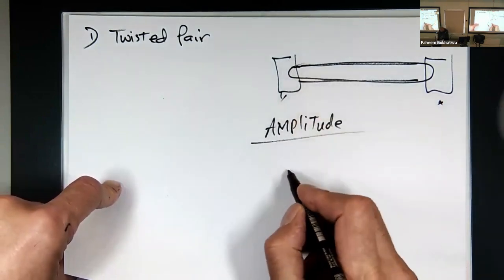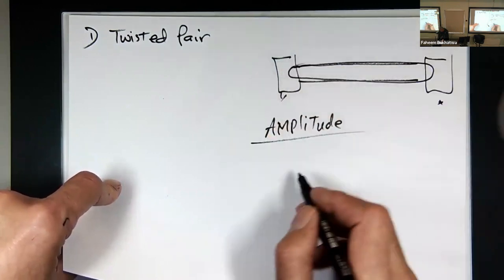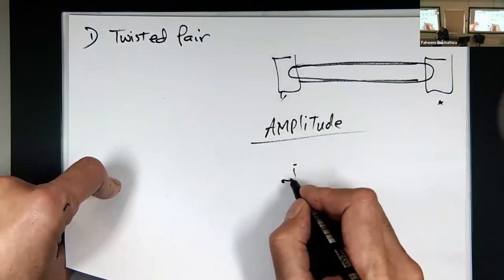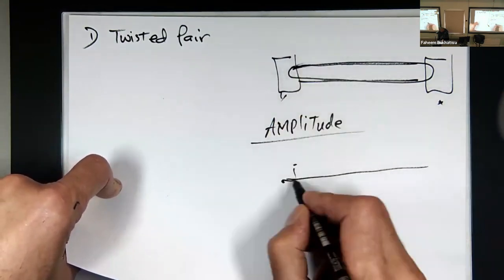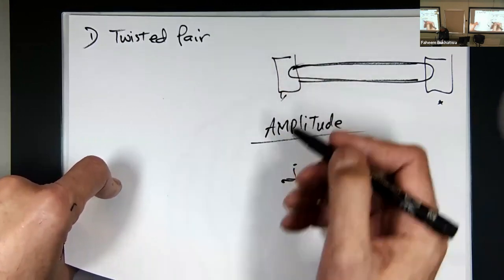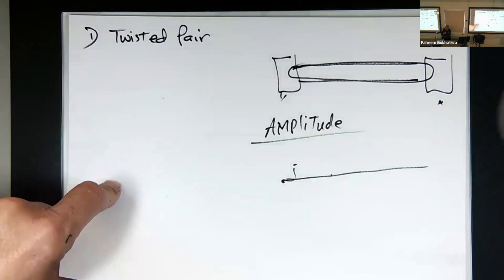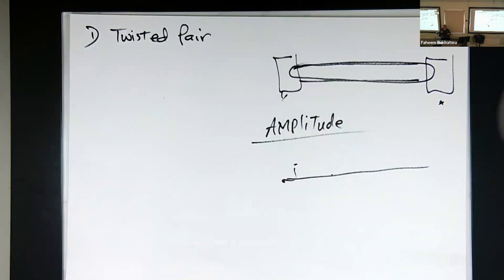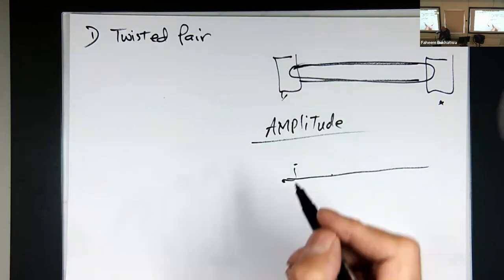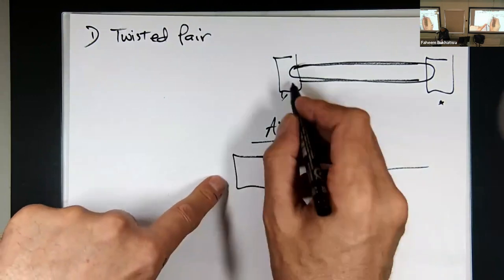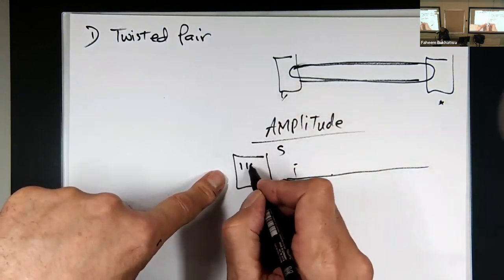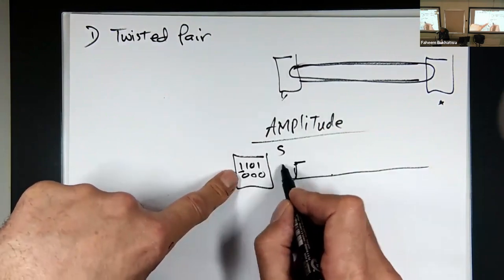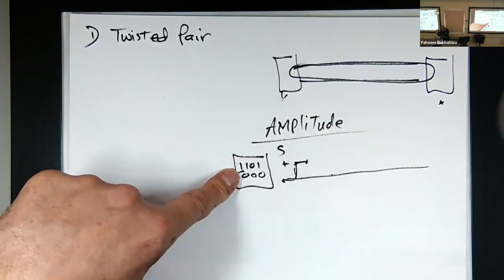So for example, if the electric signal that's flowing now between these two machines is maybe 5 volts or 2 or 0 volts, just continuously going 0. But if we want to send ones and zeros, the two sides must agree. For example, we agree 5 volts means 1, minus 5 means 0. We both agree that. Then I start looking at my data here. I am the sender. And I see 1, 1, 0, 1, 0, 0, 0. That means bring up the voltage to plus 5.